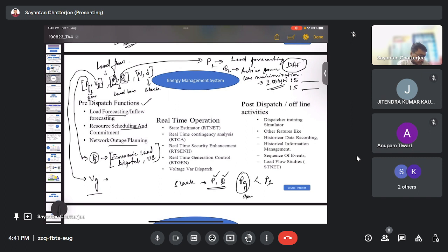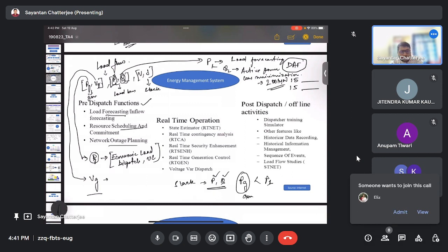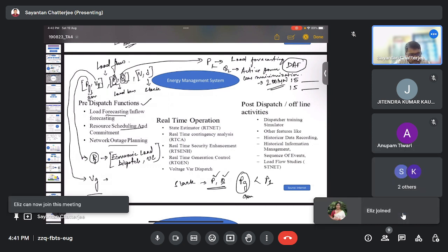So we can't consider it from a slack bus perspective. The slack bus has to cater to the system losses in a participative manner, and battery storage devices don't have that much capability to deliver. It is generally taken into consideration that the higher rated generators would be considered as slack buses, which have the ability to deliver the losses on a higher scale.